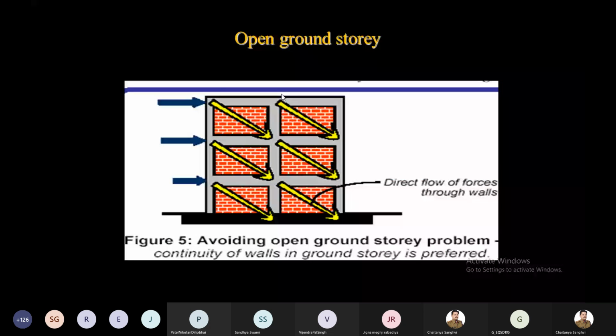So what are the remedies of the soft story effect? We know that on the upper story we have columns plus walls, right? So if you provide the walls at the ground story, then the soft story problem is solved, because the stiffness of each story will become the same, right? This problem can be solved. But here, what is the problem? By placing the walls, you are sacrificing parking. So parking you cannot have in this kind of solution. So it is not acceptable.